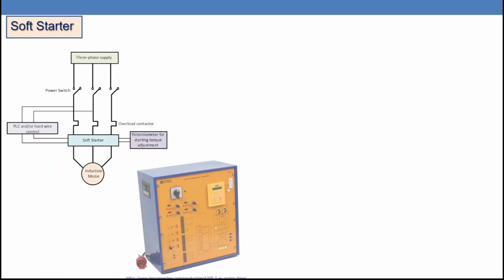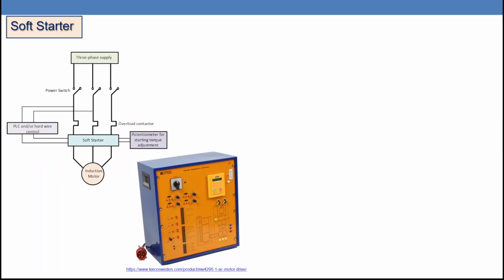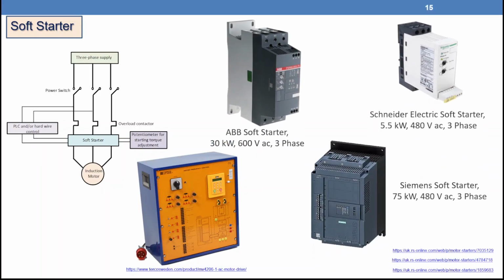So in our lab, we can have a device like that one. That one is a complete drive, but we can use that one as a soft starter. Also, our students can build that one as a final year project. In the industry, you can use a drive like that one for speed control, and at the same time you can use that one as a soft starter. It ranges from a few kilowatts up to a few hundred kilowatts.